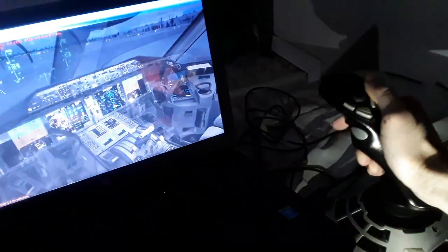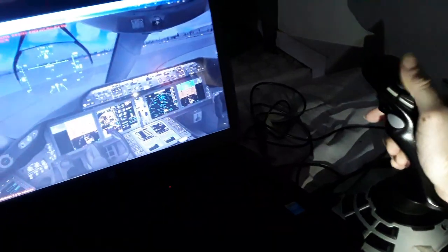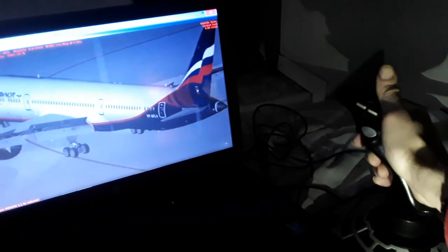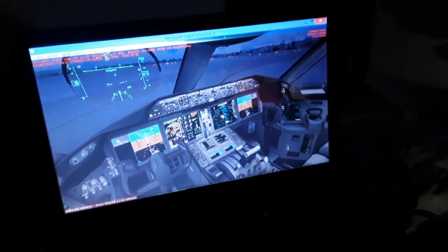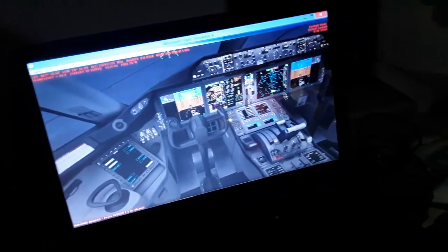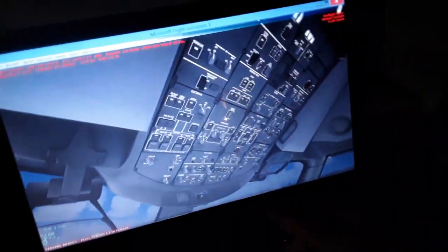So we need pressurization from the engines for cabin pressurization, wing and engine anti-ice, oxygen regulation in flight, also for air conditioning ventilation, and for hydraulic fluid tank pressurization. When we move the flight controls here, that you see, we need hydraulic fluid pressure, so it's air pressurized from the engines also, so you can move the flight controls around, the elevator, the tail. Also landing gear extend and retract, thrust reversers from the engines, nose steering and parking, and normal braking, so hydraulics.